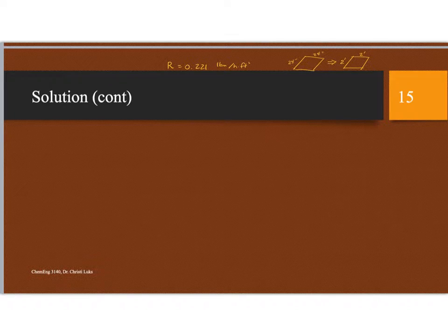All right, so we know the geometry is a plate that's 24 inch by 24 inch, or since we're working in feet, 2 feet by 2 feet, and then it's 2 inches thick. The drying is going to be from both sides, so the area is the area of one side, 2 foot by 2 foot, multiplied by 2 because it's both sides.